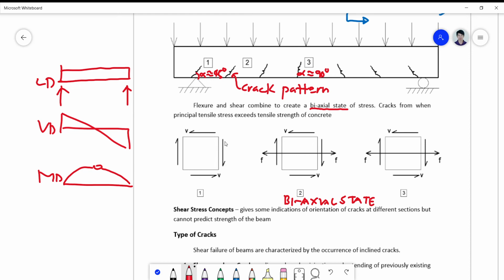No, it tends to slide the surface. It tends to slice the surface or to cut the surface into two, such that this V here corresponds now to your shear stresses, which if we look into the concept of equilibrium, this shear force here must be equal to this shear force when you sum up forces horizontal.